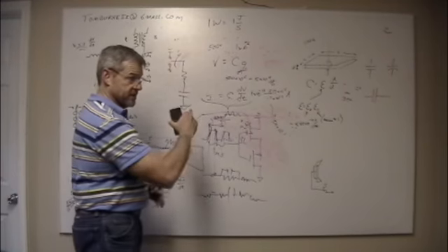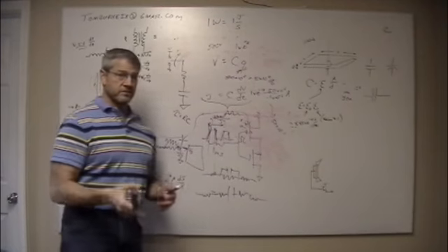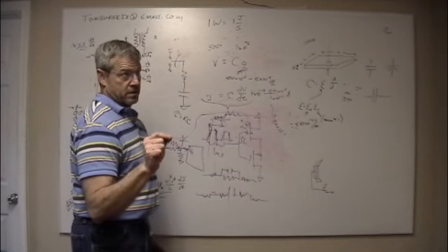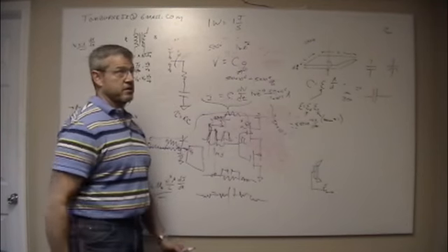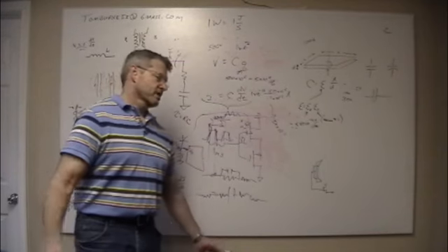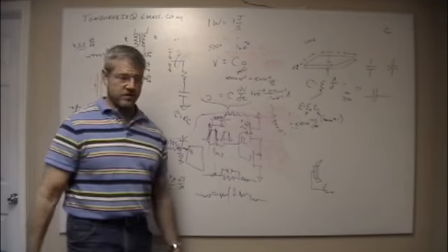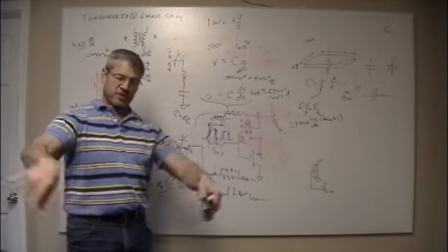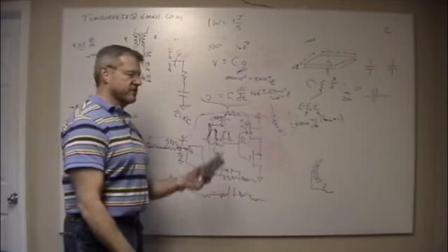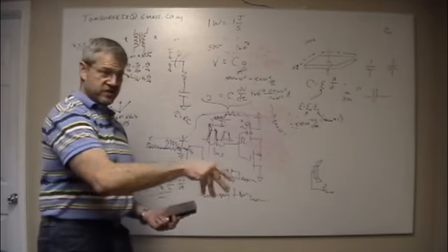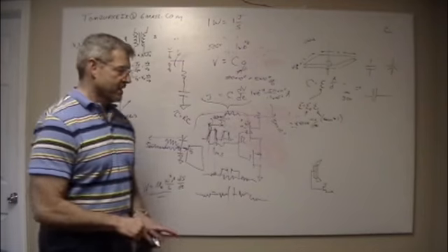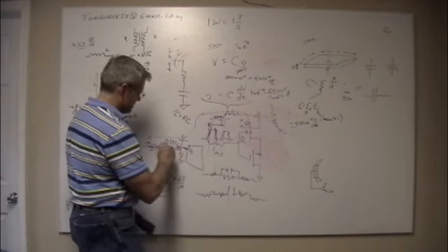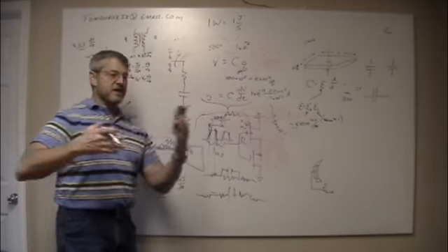those are called bypass capacitors. To do the bypass capacitors correctly on your circuit board, people usually just throw in a 10 microfarad, a 1 microfarad, and a 0.1 microfarad. That worked in 1 megahertz and 5 megahertz circuits back in the early 80s on PC boards, and people just sprinkle them all over the place. As a rule of thumb, they could actually be making the problems worse, because you've got this track resistance and this track coming in that has some inductance, which we'll talk about in a minute, and you're making a resonant circuit.